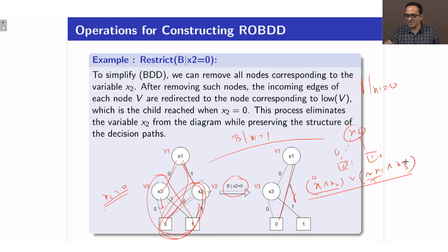So, this basically results in x3, right. So, if I take this function and restrict it with x1 equal to 0, it results in the value x3. So, whether this is a BDD or a Boolean expression, I can restrict that function on any variable and get a reduced-size BDD or reduced-size expression. Okay. So, the restrict we understood.